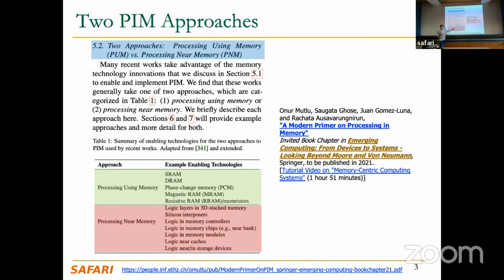Logic in memory chips is something that we have already seen as well, near the bank, such as the PEI microarchitecture, or proposals from Samsung and from SK Hynix. We will review them all again today. Logic in the modules, we have seen the AxDIMM example. We will have one slide about it as well today.